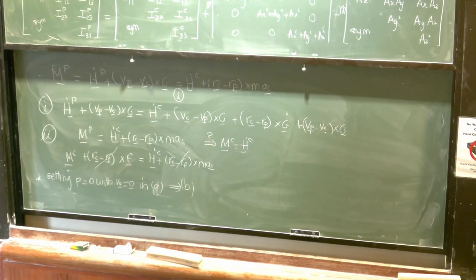I'm kidding. So what we want here is that, okay, a uniform slender rod rests on a car seat as shown. Determine the deceleration A, so the car is decelerating, for which the rod will begin to tip forward. The rod is not tipping forward, but it will begin to tip forward. What does that mean in terms of forces? If the rod is about to tip forward, but it hasn't tipped forward yet, what is the angular velocity of the rod? 0, because it did not tip forward yet, but it's about to tip forward. So what does that mean in terms of forces?